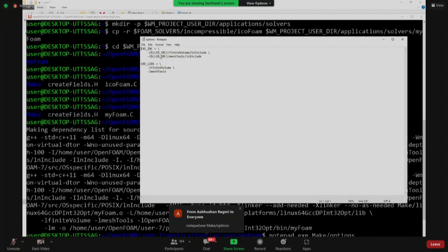So later on, let's say you want to incorporate a turbulence model, you need to source the turbulence thing, you need to say Lagrangian multiphase model. If you see those solvers, you will see a few more lines, and you can estimate how you are going to modify your own solver, whether you need to incorporate new things or remove some things. So this is a very basic thing. We just need to add equations, so we don't need to add anything here.